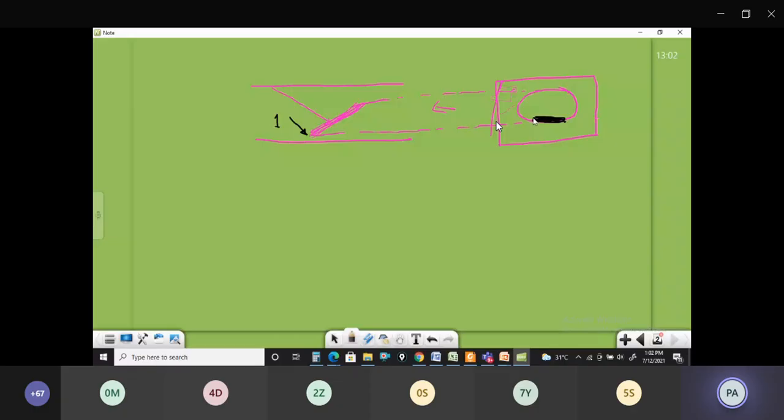if the total area of the ultrasonic wave covered in this region is say this much, I can say this is covering say 25%. So if I draw the echo pattern, then you must also understand the distance traveled to go this much down. This beam path is bigger than this beam path. So what will happen? I am moving the probe in this direction, so I will get somewhere farther away from the origin.